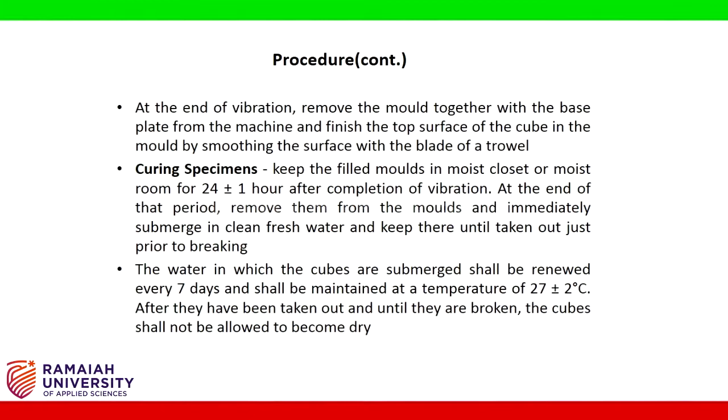Curing specimens. Keep the filled molds in moist closet or moist room for 24 plus or minus 1 hour after completion of vibration. At the end of that period, remove them from the molds and immediately submerge in clean fresh water and keep there until taken out just prior to breaking. The water in which the cubes are submerged shall be renewed every 7 days and shall be maintained at a temperature of 27 plus or minus 2 degrees Celsius. After they have been taken out and until they are broken, the cubes shall not be allowed to become dry.